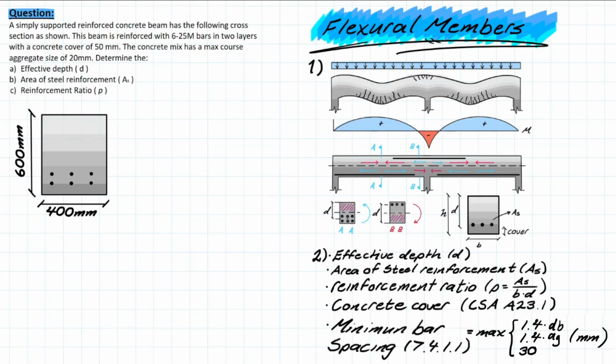And depending on where it is, specifically, for example, if you had a footing, you're going to have a much higher cover because that footing is exposed to the earth. And earth, obviously, can have a groundwater table, and water can seep into this member. So you want a larger cover to prevent that. So those are some basic design principles for why cover is chosen. And another important design requirement is going to be based on your minimum bar spacing.